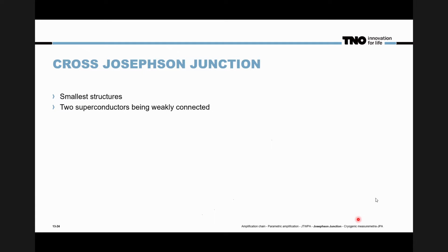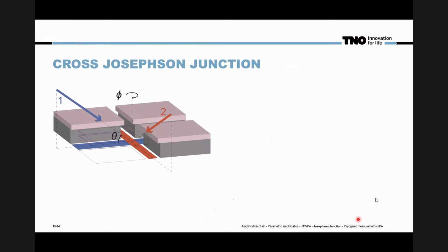And there are actually several different ways to fabricate this type of Josephson junction. But the method I used is known as the bridgeless method, which creates the Manhattan-style junctions, also known as cross junctions. So here we see a schematic of what's happening.